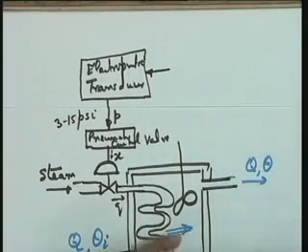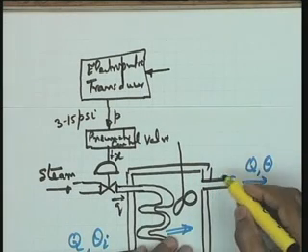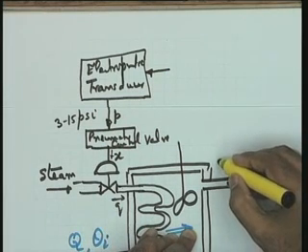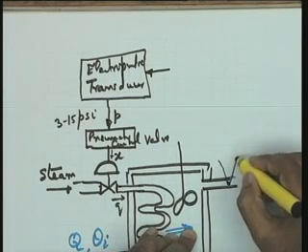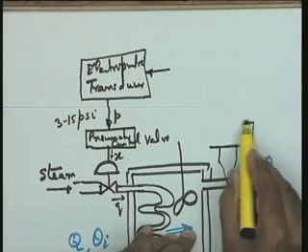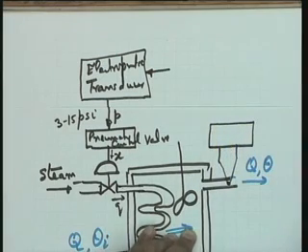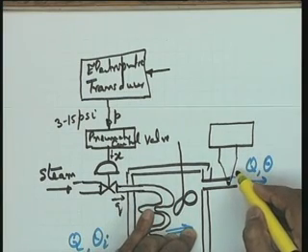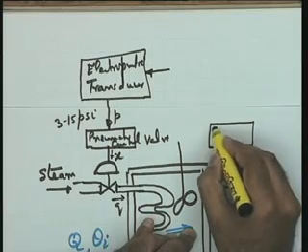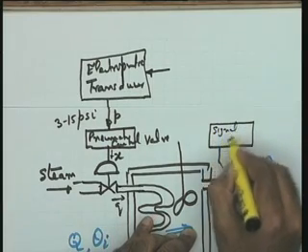Let us take the sensor point. Thermocouple, okay, we could take the thermocouple, though the alternatives are there. Thermistor and other things are there, but thermocouple is a very simple device. So, I am using a thermocouple here. The thermocouple will have to be interfaced to an appropriate signal conditioner, because this voltage may be too low, and secondly I need a current signal for transmission. So, this is a signal conditioner.